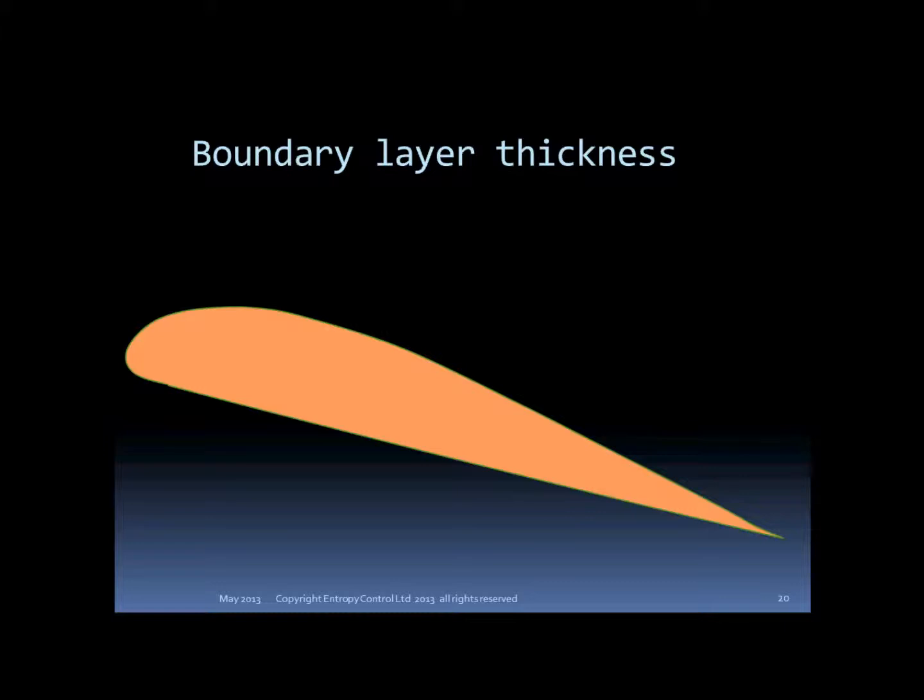But for moderate angles of attack, the flow behaves reasonably, although the boundary layer does get thicker towards the trailing edge on the top. Now, boundary layer theory, plus the results of numerous experiments, allows us to predict boundary layer behavior quite accurately for different surface roughness and pressure conditions. So, as we know the pressures everywhere, we can predict the boundary layer behavior quite well.